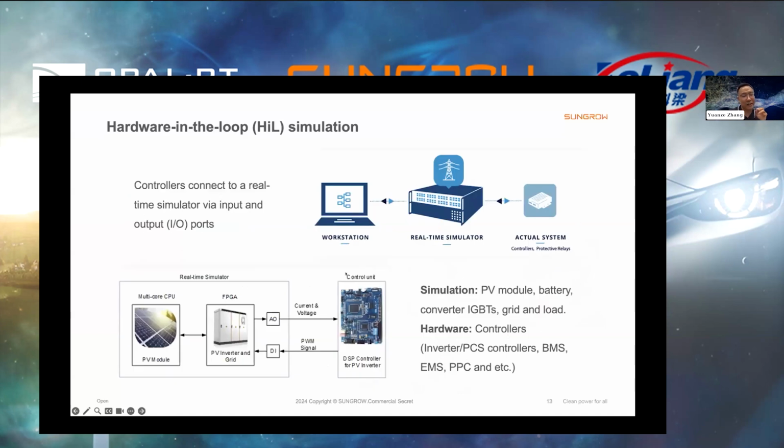Okay, once we can achieve real-time simulation, actually we have a new pathway of simulations that we can connect. I consider real-time simulation as a pathway that connects the digital world and our real world. We can build PV modules, batteries, converters, IGBTs, or grid and loads in a real-time simulator, and then connect our hardware controllers to the system, like inverter or PCS controller, BMS, EMS, and PPC controller, etc.